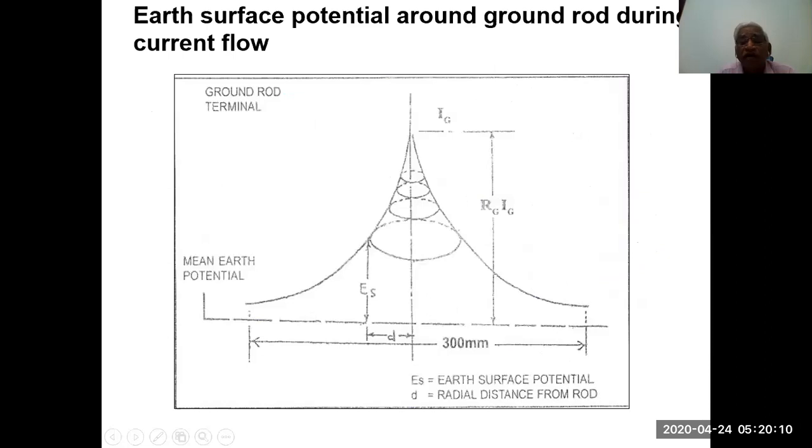Here also is shown the zone where the potential at the point of an earth fault will be more, with more current during the earth fault. The potential is high. As you go away from this, 300 meters, the potential will drop down around the electrode.